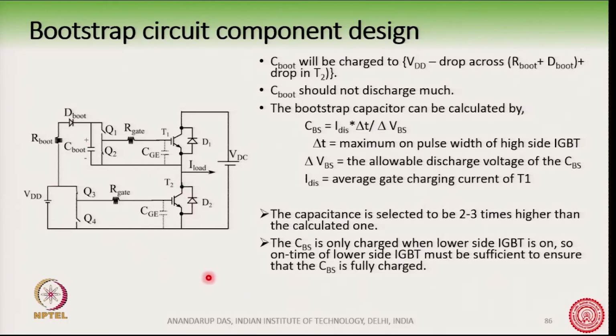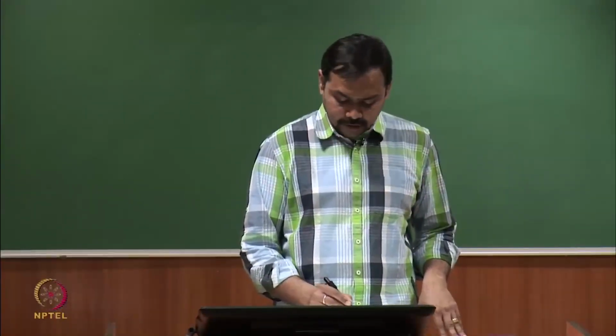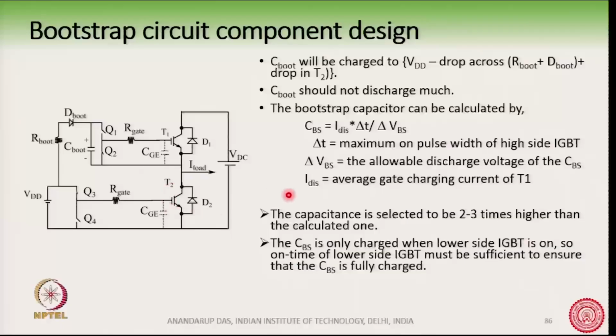In fact, for many such Bootstrap circuits, the first pulse should be on the lower IGBT, because when it is turning on, C boot may be fully discharged.